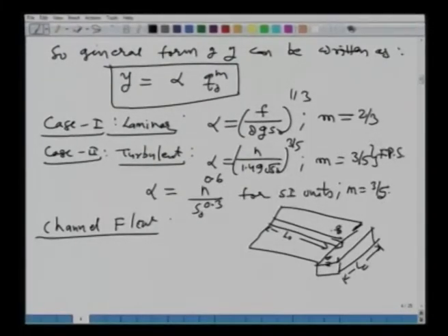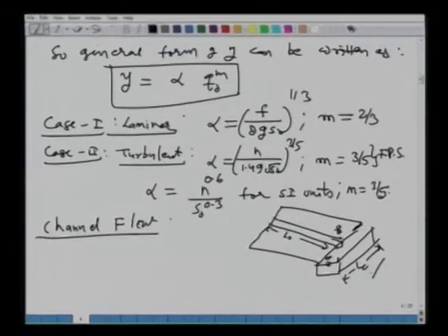Okay. So, what you can do is you can divide your overland flow into different strips, all right, of either the unit widths or any other widths. Okay. And then you can calculate this Q0, all right. The equations we have already seen. This Q0 will be coming into the channel, and then the flow will be going in the topographic direction or the favorable slope. Okay. So, let us say in this case your flow direction is, let us say, this. Okay. So, you will have these Q's coming in here, all right, at different lengths, and then you have the depth of flow is y here in the channel and the velocity is v.